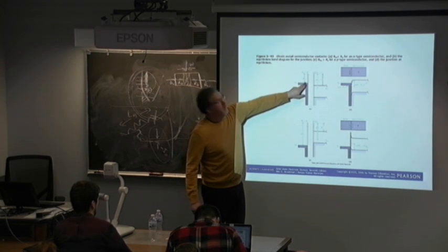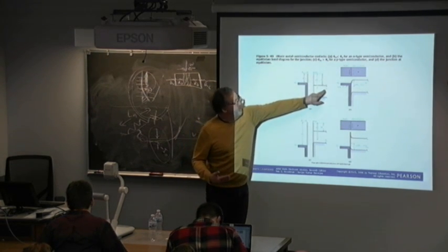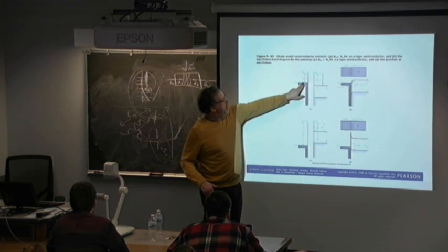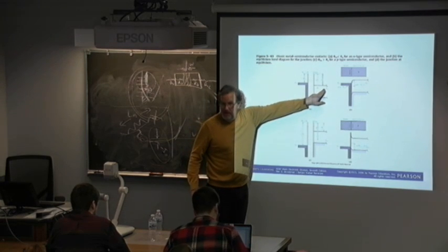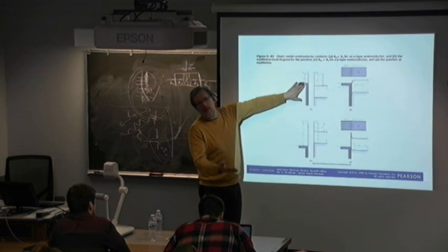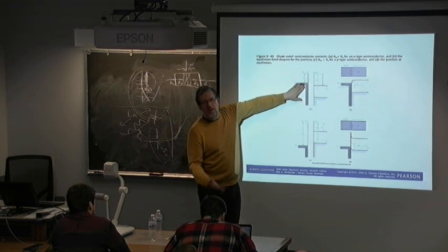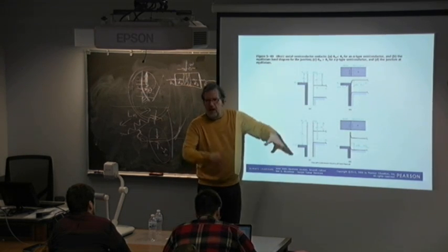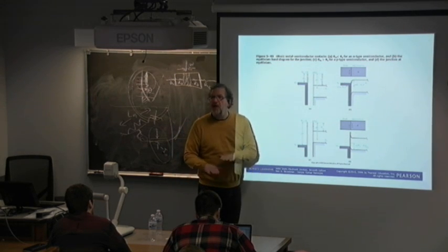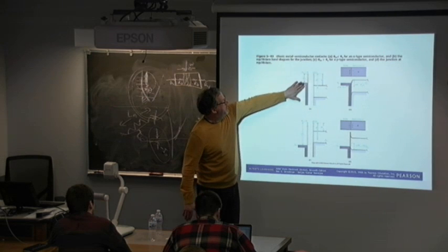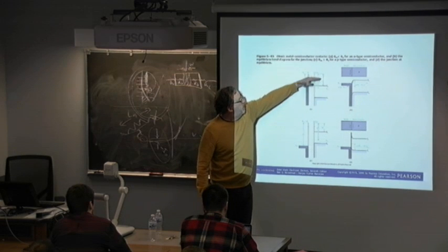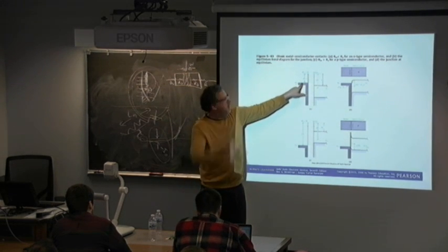So then the metal here has a higher energy with respect to the Fermi level of the semiconductor, right? So therefore, the metal either has to lower with respect to the semiconductor to bring it into balance, into equilibrium, but the metal's metal. It's not going anywhere. It's loaded with electrons. It's like trying to take a bucket of water out of the ocean. You know, sea level is still going to be sea level. You're not going to change it. It's too many electrons. So that's going to be rock steady. So the semiconductor has to then come up with respect to the metal. Okay, so that's what I've got to do.